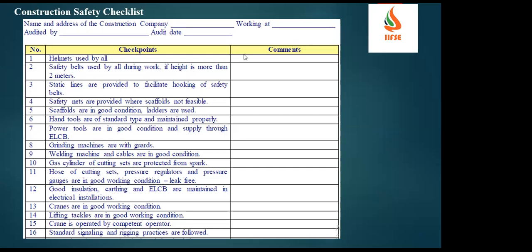Wire rope, for the vertical, if you are making it as a lifeline, okay sir, vertical polyester, okay sir. If they are using it as permanent, they will go with wire rope. Otherwise, for temporary activities they will not go for wire rope, especially in the construction industry.